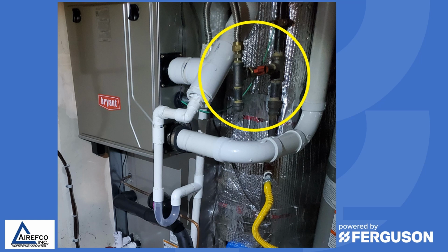So this was a real liability issue on the part of the installer, that he did not install a drip leg. And something as simple as that could have caused a real problem for him and his company as they did this installation on this gas furnace. So this is why I'm stressing so strongly that when you install a gas furnace, make sure that you're installing it with the recommended venting procedure by the manufacturer so that you don't have any liability in the installation.